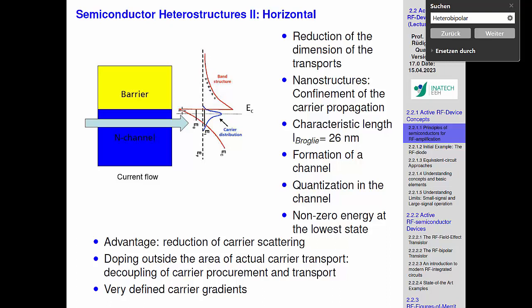And now something happens, and this is designed, that this band offset energy crosses the Fermi level. So this goes under the Fermi level. This is good, because the band under the Fermi level means that the carriers are in the range where the electrons can conduct. They are in the conduction band, and this is where they can move. Yeah? So what have I reached here? I have reached a situation where very close to this interface, the electrons want to be. So here in this part. And they stick there very close to the surface.